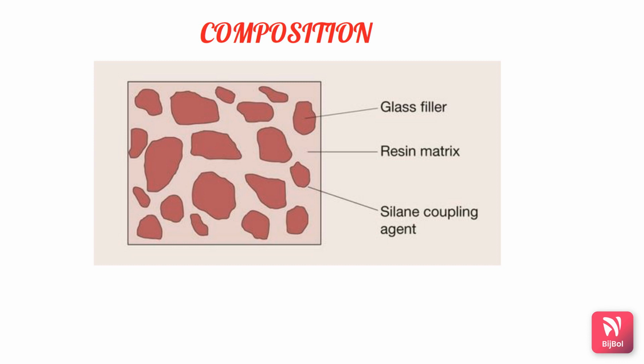Now we'll see the coupling agent. The coupling agent binds the filler particles to the resin matrix and allows the more flexible resin matrix to transfer the stresses to the stiffer filler particles. Now we'll see the activator and the initiator systems.